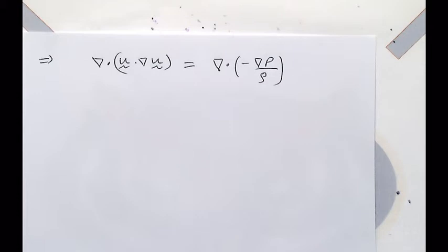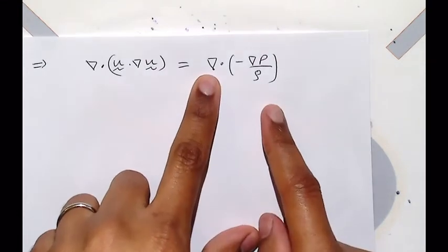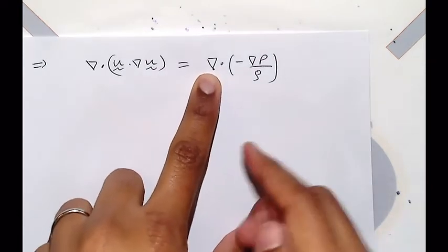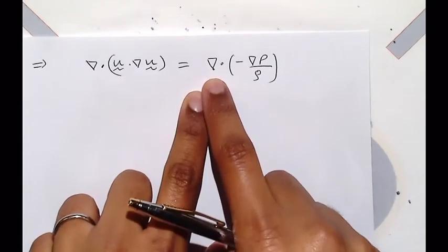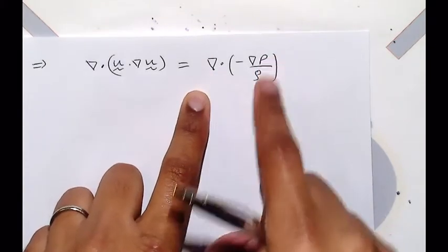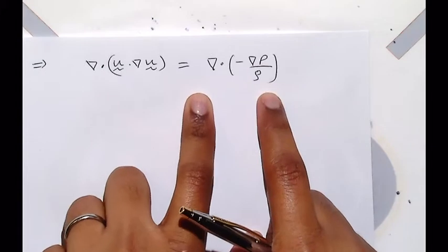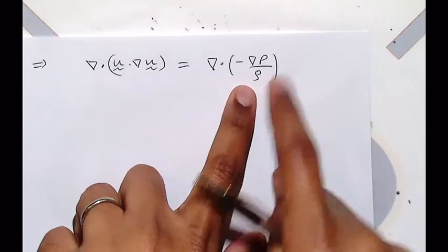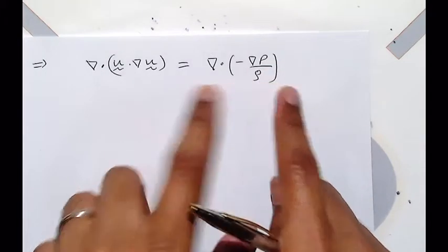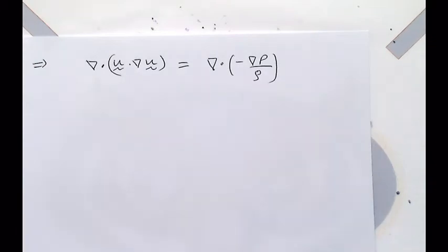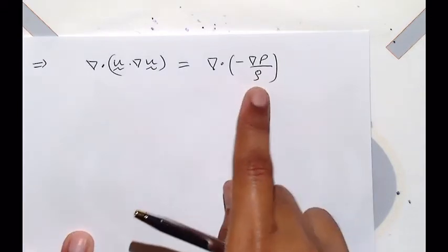So this is just a derivative. If we talk about 1D, this would be d by dx. And there are two terms inside, so we logically should take the derivative of both of them. This is the chain rule. But again, let's say the fluid is homogeneous. There's no dependence of rho on space, so we can assume that's a constant and pull it out.